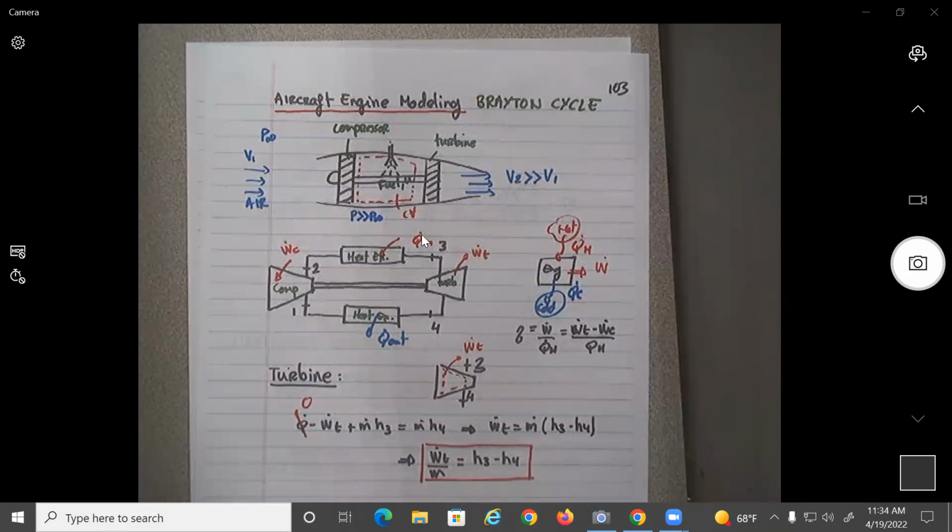So over here, I start by looking at the system turbine. You see the turbine creates work, so we're just looking at this term over here. If we neglect any heat exchange with the outside, we find that the power created by the turbine per unit mass flow, should be an m dot, is H3 minus H4.